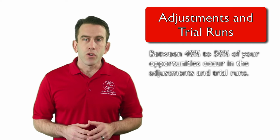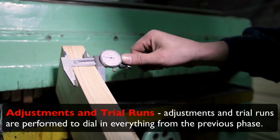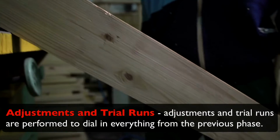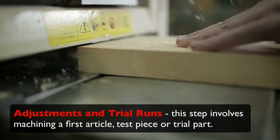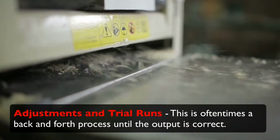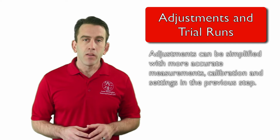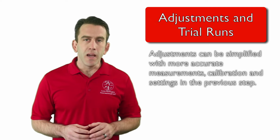The final phase of a traditional setup is the one that traditionally takes the most time. In phase 4, adjustments and trial runs are performed to dial in everything from measurements, calibration, and the settings phase. In general, this step involves machining a first article, test piece, or trial part. Then it is inspected and adjustments are made. This is oftentimes a back and forth process until the output is correct. These adjustments can be simplified by having more accurate measurements, calibration, and settings in the previous step. This is easier said than done in many cases.